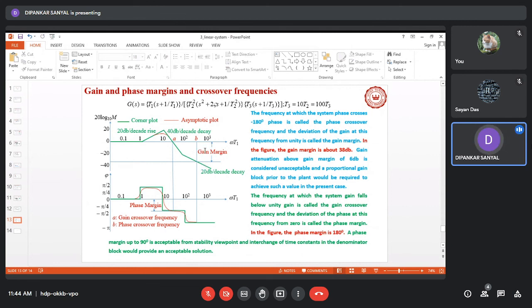So if we jack it up by say another 34 or 35 dB, we resolve the problem. The other situation could be, if this time constant is in our hand, we just interchange this T2 and T3. That will also resolve the problem of the gain crossover frequency.